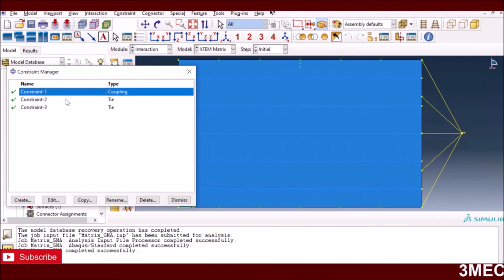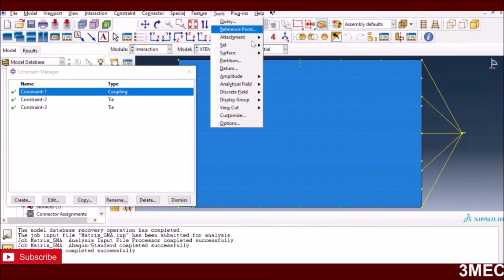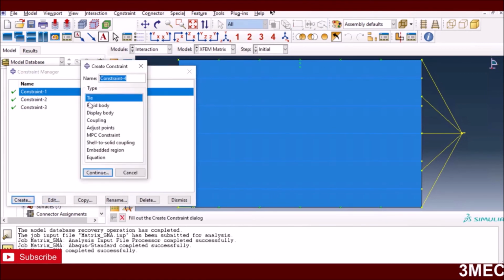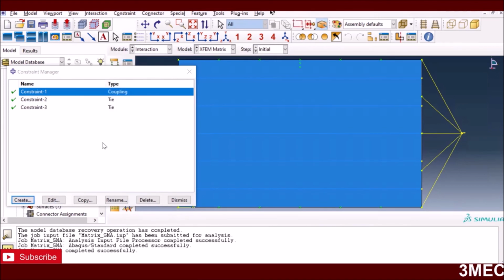So now the important part is how to apply the boundary conditions. I created a reference point. If you remember, to create a reference point you go to tools, create a reference point, and then click on any coordinate where you want to create it. Then if you press create constraint, I use this coupling option here, which will couple all the kinematic constraints of the whole surface with a specific point.